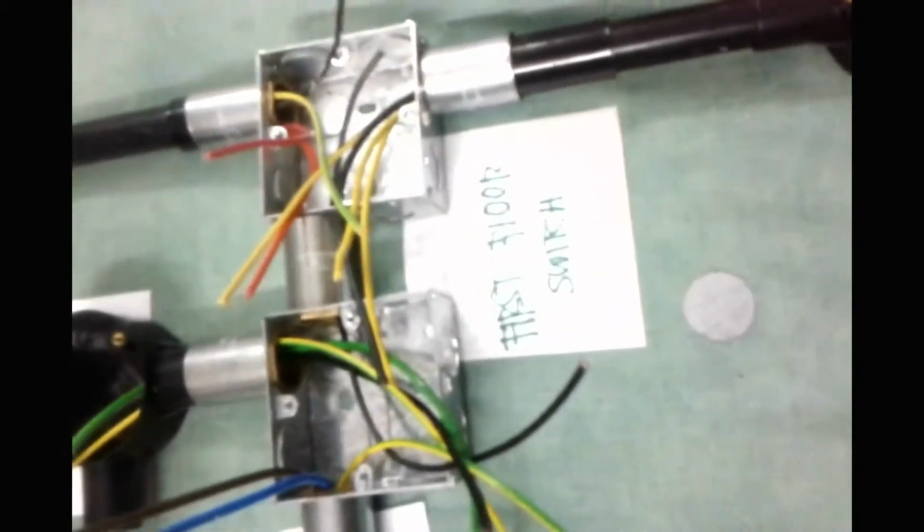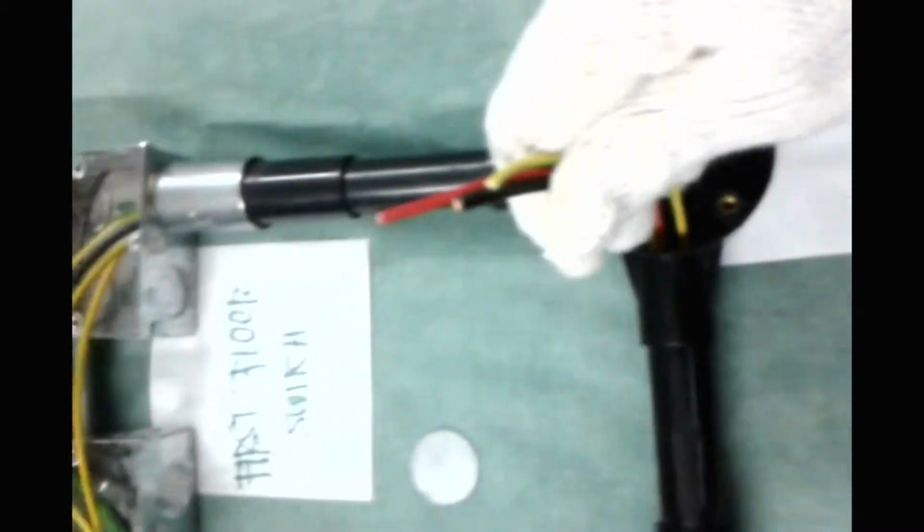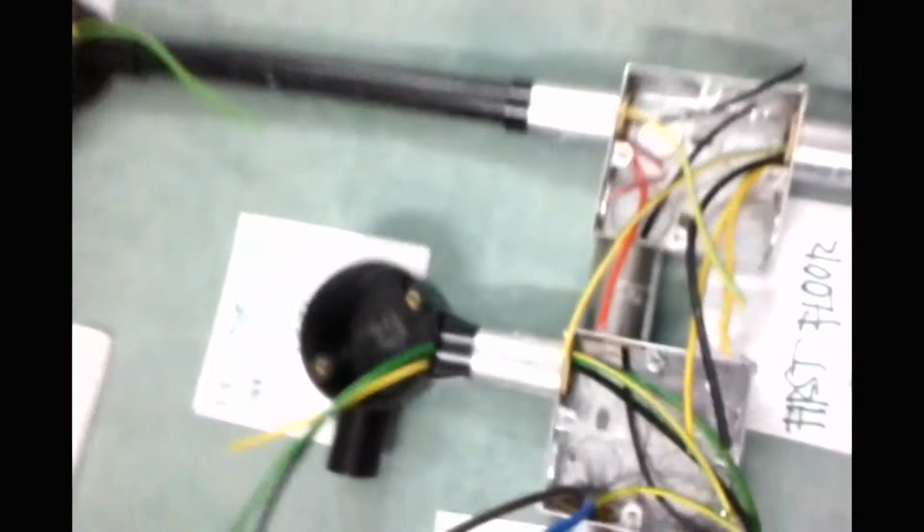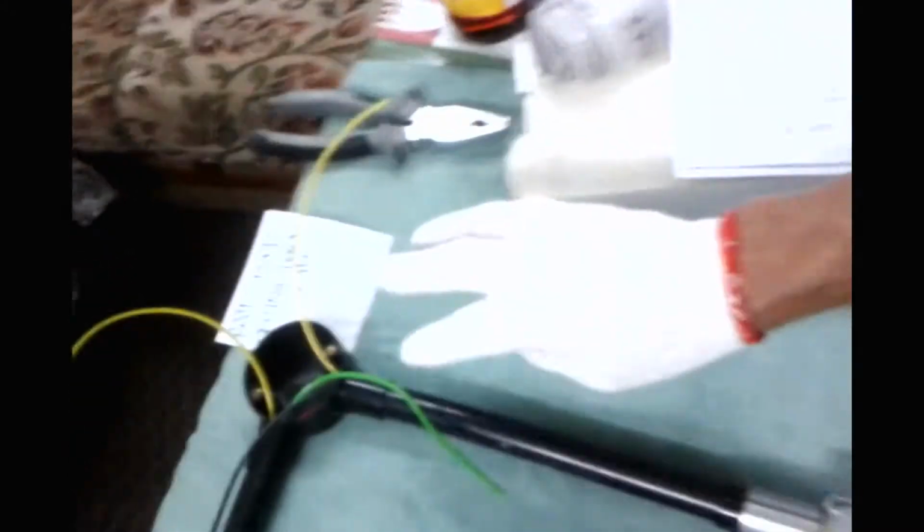and for the power supply we have this blue as our line 1, and this brown will be used for our neutral line, and we have our earth wire. So first we are going to do is we will connect our lights. So for our wall lamp, for our first floor entry ceiling down light, and for our roof floor ceiling down light. So we will connect these 3 lights.